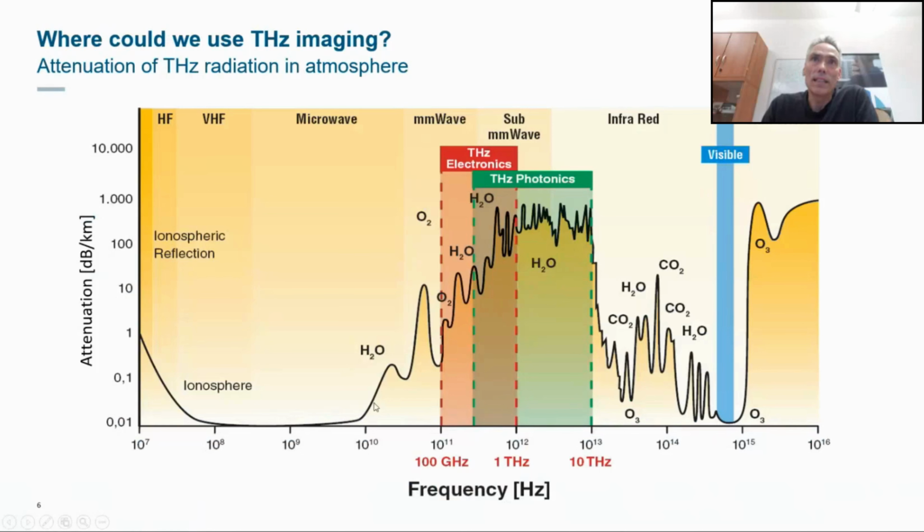And what you see here is that in atmosphere, you have very pronounced, strong resonances of various kinds of gas molecules. This is water, oxygen, for instance, causes vibrational and rotational resonances, which already show that there's a strong interaction between terahertz radiation and gases, as well as solids. Although in solids, we don't have that many strong resonances like in gases, and therefore what we are typically trying to do is to measure the permittivity, which is the dielectric constant of a solid. And we use that for identification of different materials and tissue, also in this work that I'm going to present.